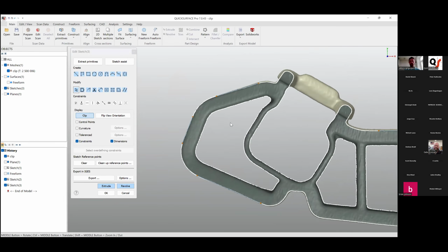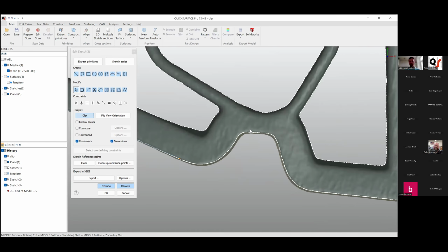And at the same time, if you're holding Control and brushing over the endpoints of lines, it will automatically connect these two lines at the intersection. And if we repeat this on the same corner, it will automatically create a fillet based on mesh data. Yes, actually, we can create fillets everywhere also, so we have less work later. This is 5. I'll quickly create some more lines.